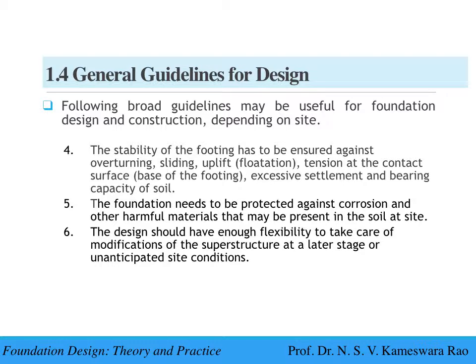4. The stability of the footing has to be ensured against overturning, sliding, uplift, flotation, tension at the contact surface, base of the footing, excessive settlement and bearing capacity of soil. 5. The foundation needs to be protected against corrosion and other harmful materials that may be present in the soil at site. 6. The design should have enough flexibility to take care of modifications of the superstructure at a later stage or unanticipated site conditions.